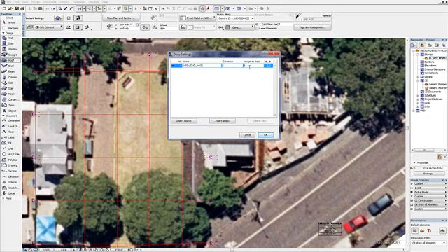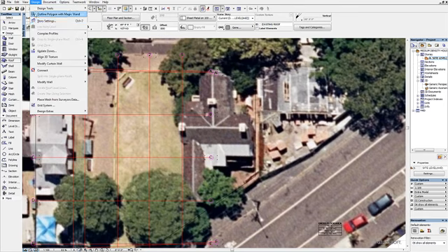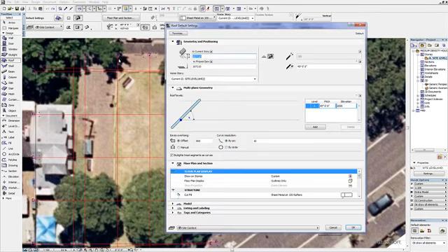However, if we've got story settings that begin from an elevation level that is not 0, say for example 100,000 is the start of the first story, then the RL to project 0 will be different to the RL to the current story when looking in the roof tool.